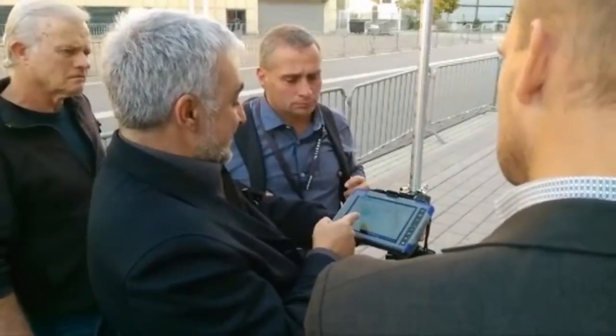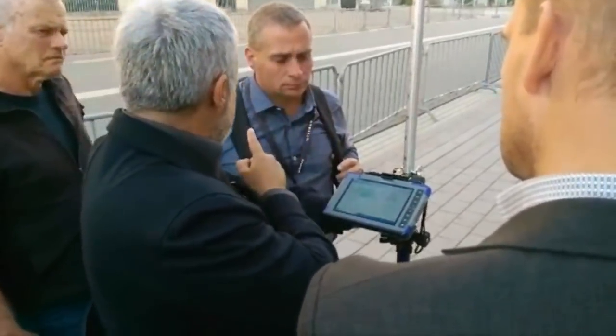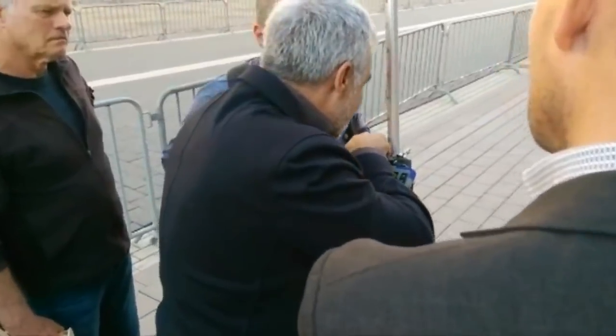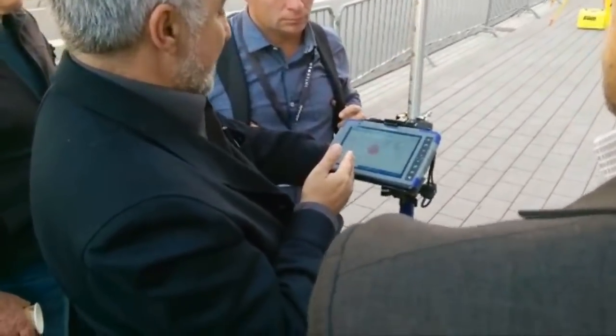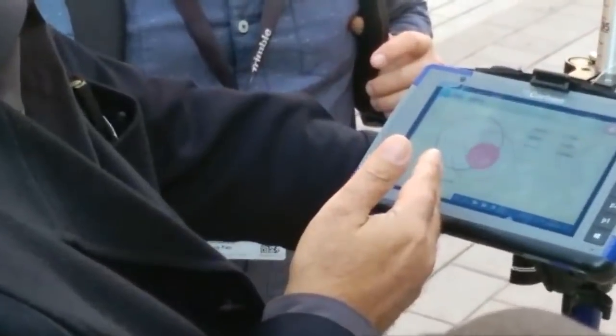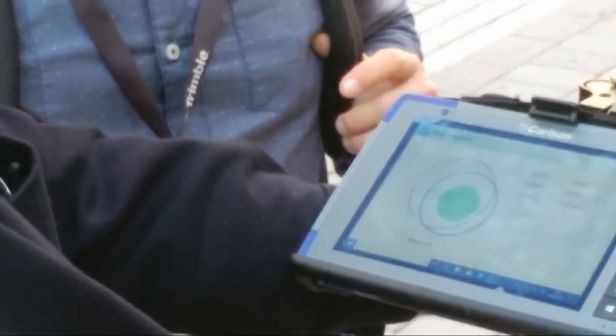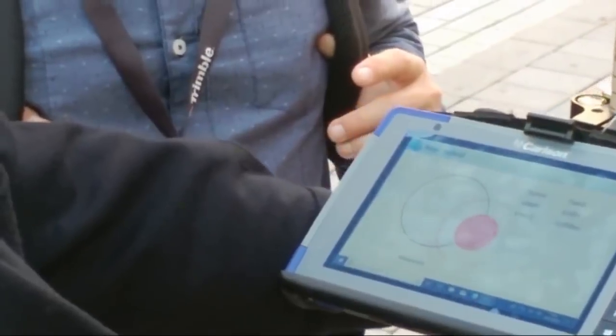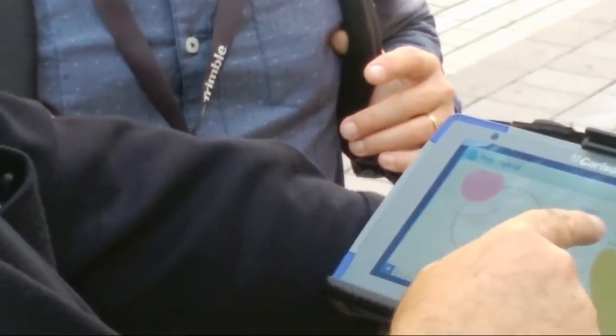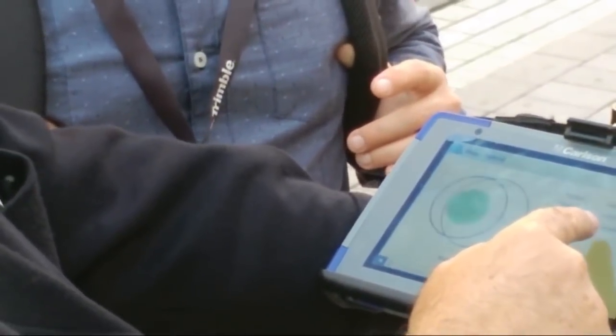Okay, this is a sensor from the GPS. If you have sensors, you use them; if you don't, then you have to look at the file, right? But if you have them, you use them. So if I have an electronic bubble feature in my GPS, why not use it for the prism? If I can level the pole with my GPS, why not tilt the pole for my prism? Right? That's it. If it's available, you use it. Okay? Still, I can control the quality because I'm measuring GPS too.